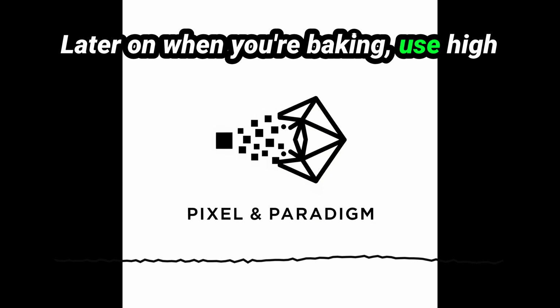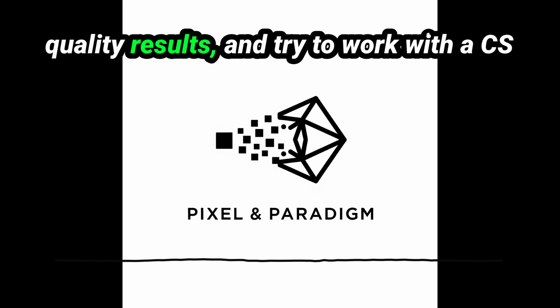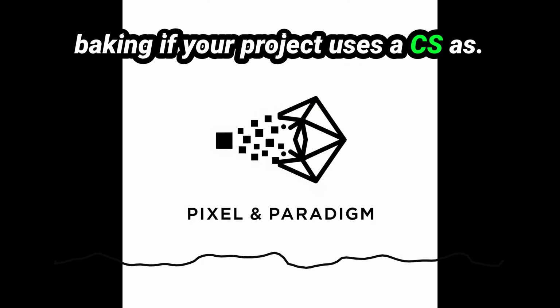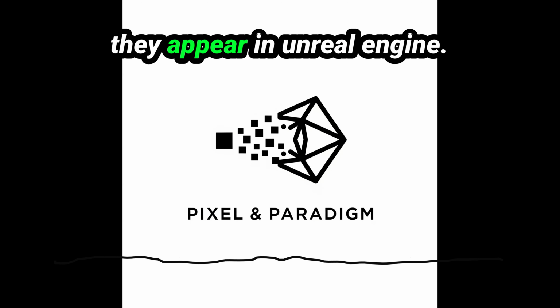When you're baking, use high secondary ray settings for maps like AO, curvature, and thickness for better quality results. And try to work with ACES color space and tone mapping during baking if your project uses ACES, as this helps ensure better consistency between how your textures look in your baking software and how they appear in Unreal Engine.